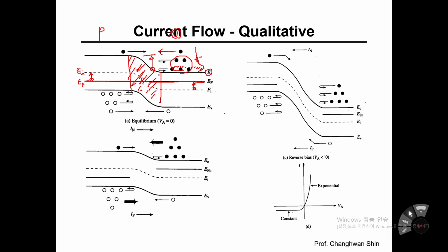However, a very tiny amount of electrons which have very high energy would freely move into the p side. Similarly, in the p side, the majority carriers are definitely holes, and those holes are distributed following the Fermi-Dirac distribution, so that most of the holes exist near the valence band edges. However, because of the potential energy barrier height across the PN diode, most of the holes can never overcome this energy barrier height. Again, just for your information, the minus y direction indicates the direction of increasing energy of holes, and the plus y axis indicates increasing energy of electrons.